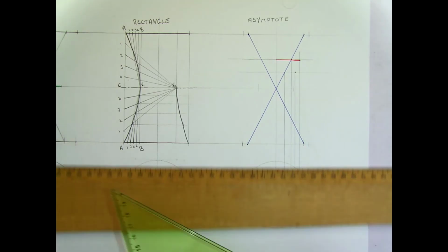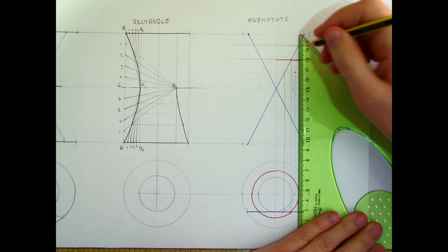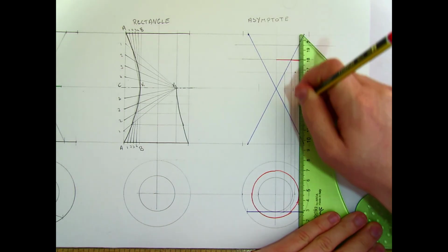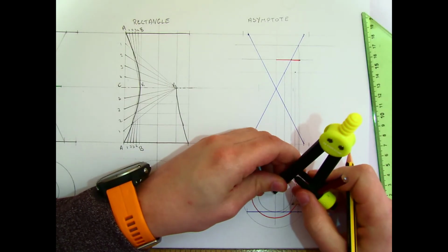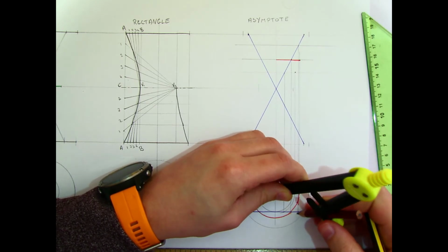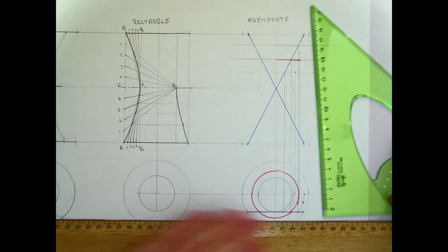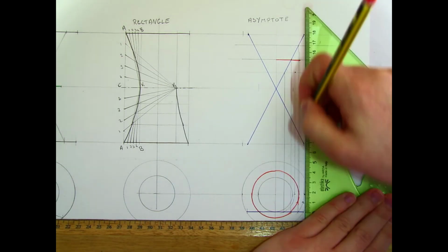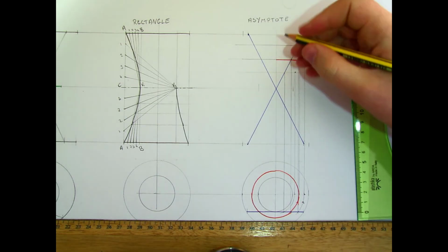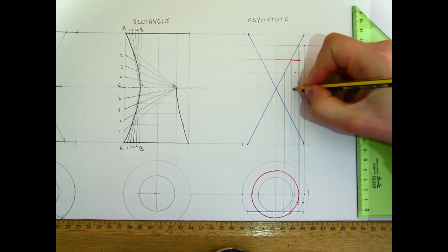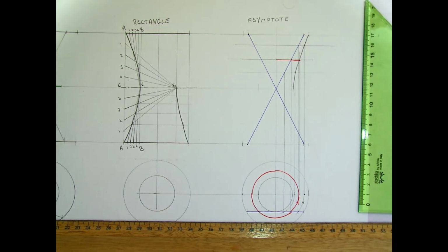I'll do one more just up above the red one. So find this down in plan. So project it down onto the asymptote line. I'm going to rotate it around until it's horizontal. So they're swinging this way. And I bring it up then to intersect the horizontal cutting plane that I have, giving me that point. So I have a number of points there. This is the throat circle, and I can join each one of these up here, forming the top part of that curve.